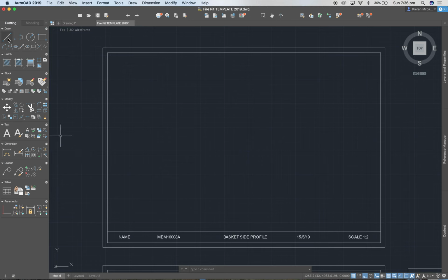Alright then, to start, we're going to look at some of the basic functions here. I'm going to go with the straight line tool up on the top left hand corner. And somewhere across the bottom, I'm going to look to draw a line. Now all I'm going to do at the moment is bring it across. Now if you have got this selected, your line will snap to either horizontal or vertical. So I want to take that off just now as it's just getting in the way. So what we're after there is the first size is going to be 200. And the angle I want is 0.